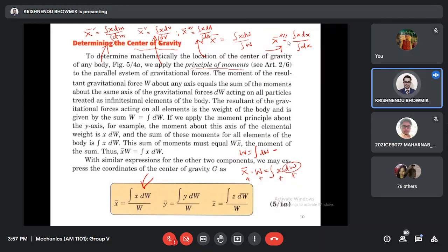That is true for solid structures. If the density is the same, the center of gravity, center of mass and centroid of the volume will be the same. If you have constant thickness of the body, it may be the same for the centroid of the area. If the 3D body has a constant cross section, its centroid may be the same as the centroid of the line. But whatever is being asked, you have to be careful that you are using the proper expression. Something in the numerator and denominator may cancel out.